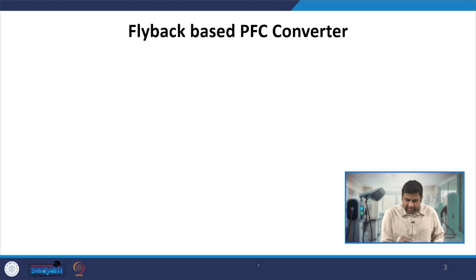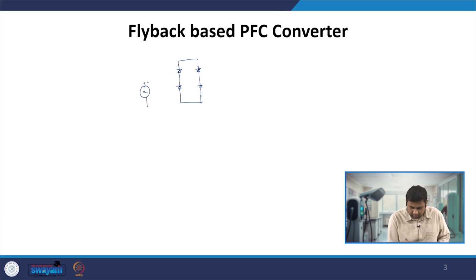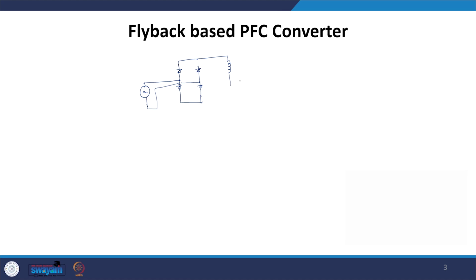In the flyback based PFC converter, we have the diode bridge rectifier at the front or first stage, followed by the flyback based converter. Let us define the switch as S1, and again we define the dot polarity in such a manner that we have a dot here.